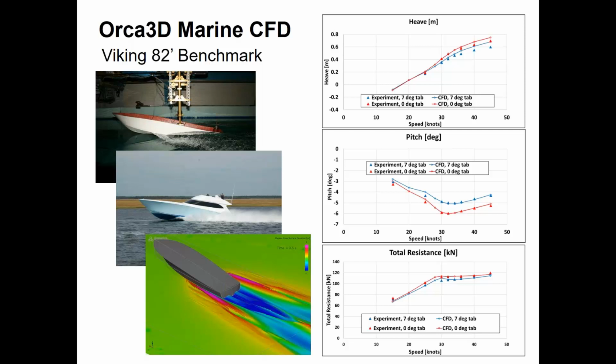But we wanted to be able to make three or four or five different variations and just run them and compare them all to each other. As simple as that, just looking at which models were producing the least resistance, the least amount of effective horsepower required for speeds, and then just start following that direction with the new designs for the hull shapes.